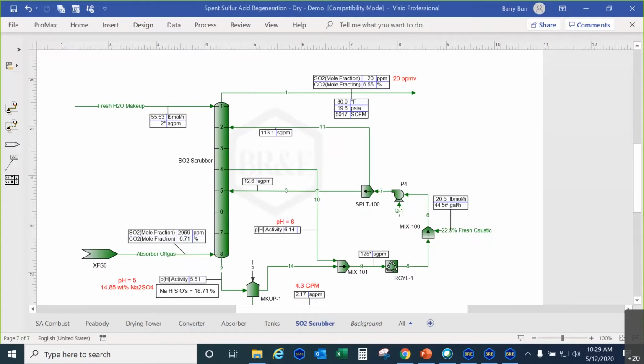I think in real life, there might be some advantages to having two burners because of the equilibrium of SO3 and SO2. Maybe those are kinetic reactions to some extent, and we're not capturing any of that kinetics in our model. We're just assuming they reach equilibrium, which is a pretty good assumption, but there might be slight differences you see with two separate burners because of the kinetics of the sulfur oxidation. That's my only guess. I don't know.